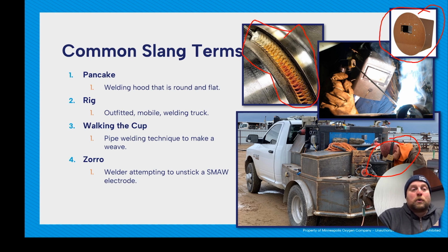Pro tip: if you do stick your rod, unhook your electrode holder and then take it off. Don't try to take it off with the electrode holder. It will just cause more of a mess. That's a bad habit.